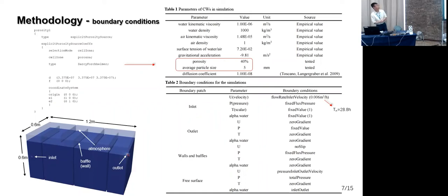And I set the T value for the inlet to one. Generally, there are two most used methods for injecting the tracer, which are pulse input and step input. In this case, the value for T was kept constant during the simulation, so it can be considered as a step input.